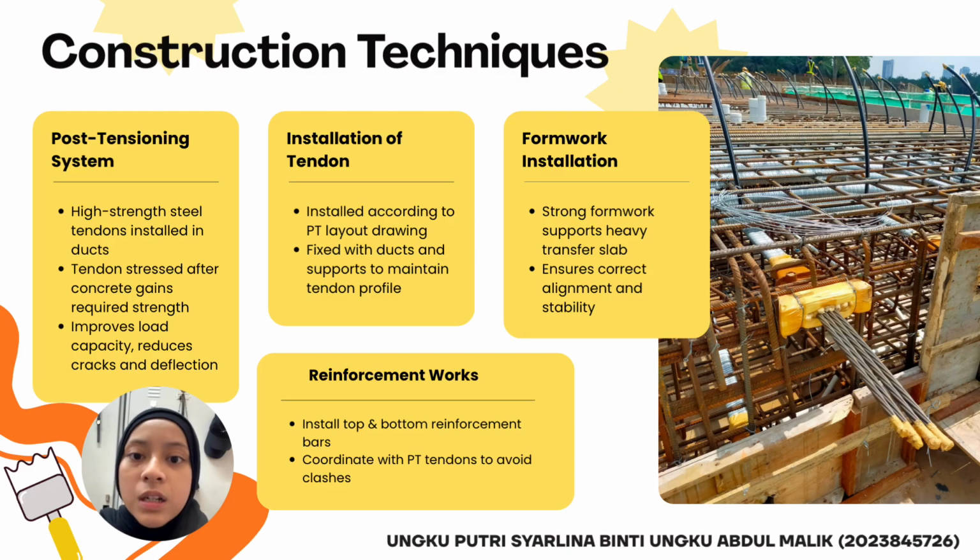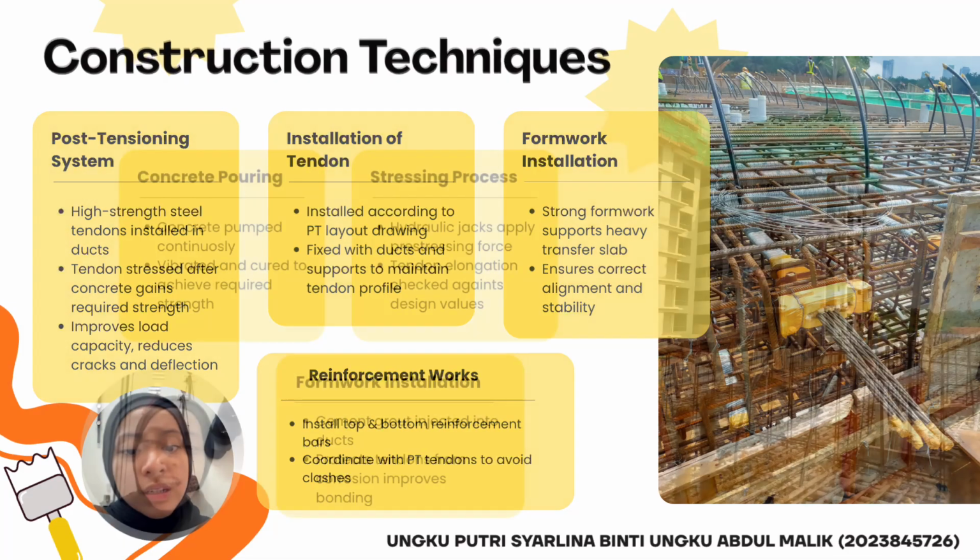So next, the installation of tendons. The tendons are installed according to the PT layout drawing, the post-tension layout drawing, the structural drawing prepared by the engineer. Then, strong formwork is installed to support the heavy transfer slab during concreting. And finally, the top and bottom reinforcement bars are placed and coordinated with the post-tension tendons to avoid any clash.